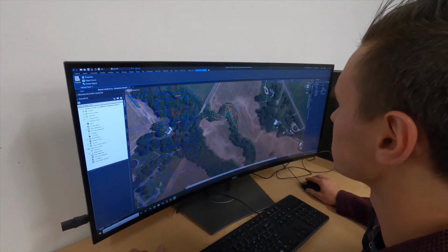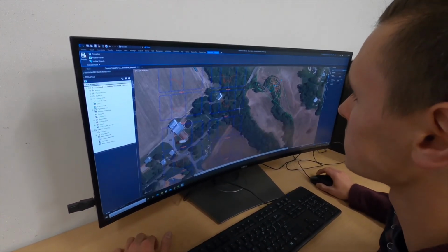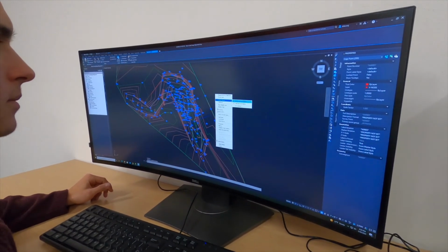After completing the topographic survey, we take those points and we put them into CAD. Once in CAD, we can take them and create an existing surface where we can pull cross-sections to be able to determine the stream type. After we do that, we're able to take those cross-sections and manipulate them based on our reference reaches to create a new cross-section and a new profile that we can put back into CAD to redesign our stream and create a proposed design.